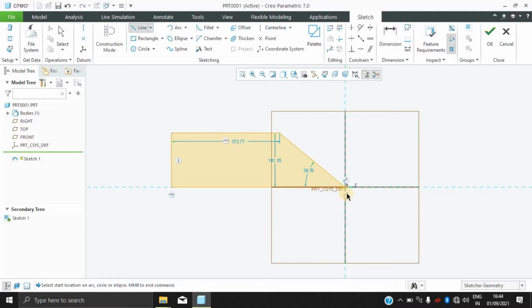Okay, now this is important to see. When you have a closed sketch, that sketch will turn yellow, so you have to consider that. You can see this option over here, this eye. If you click on this, see it is gone. If you click on this again, now it is showing me that the sketch I've created is completely enclosed. All the points of the lines are connected and there's no feature which is open. Okay, this is the closed area. This is used for showing the points, and this is overlapping geometry. So I'll also turn this on.